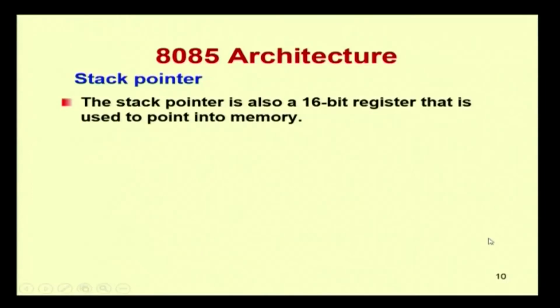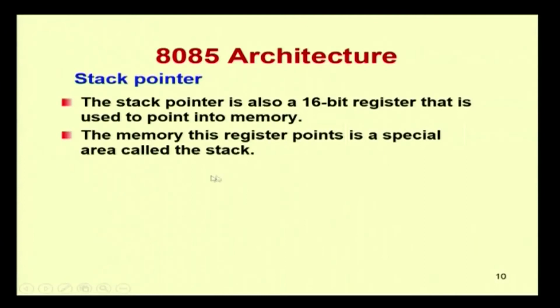initialized to point to the top of the memory. So, it will start from the highest location of the memory, and as it stores, it will point to the next lower address. The program counter will keep on incrementing and pointing. Once it takes the data from the memory, it will point to the next higher memory. But the stack pointer will point to the highest memory, and then again from high it will be coming down.